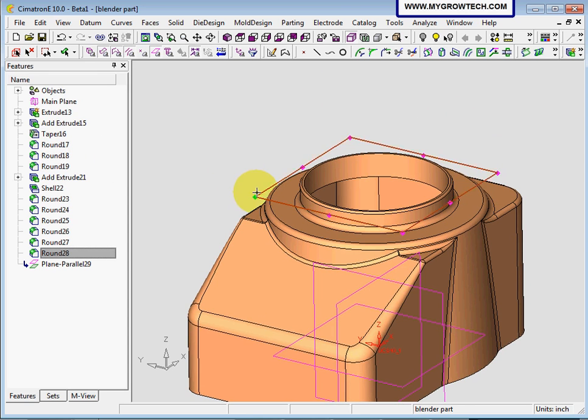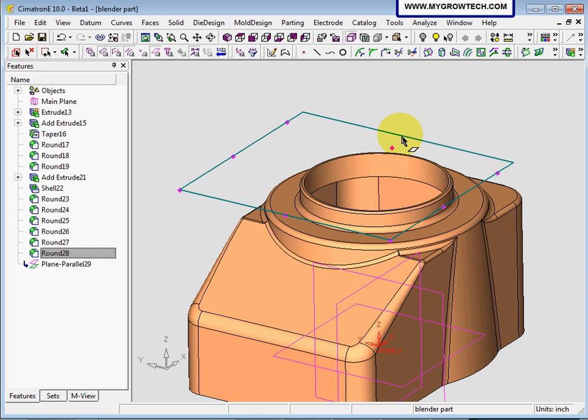Do you see when you selected a plane, at the corner you have some points? Actually, you can use these points. Click on the point. You can drag beside the plane to any size you want. It doesn't affect the geometry.